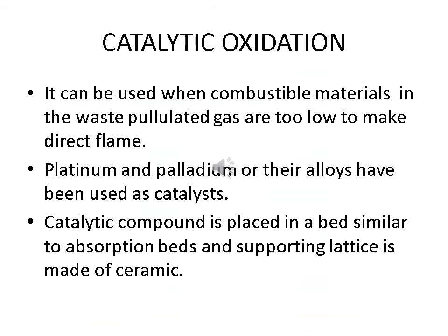Catalytic oxidation. This type of combustion is mainly used when the combustible material in the waste polluted gas is too low to make a direct flame. That means the energy of the pollutant gas is less than 3.7 megajoule per meter cube. Here a catalyst is used. Mainly platinum or palladium or their alloys are used as a catalyst.